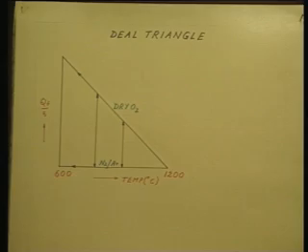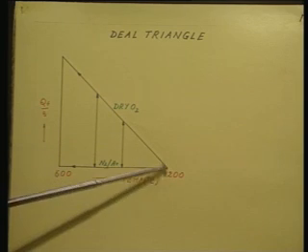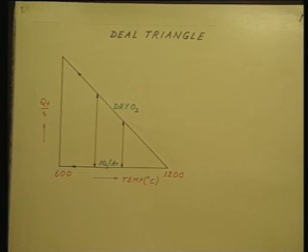So, this is actually depicted here in this figure. This is called the Deal triangle, named after B. E. Deal, who was one of the pioneers in the silicon dioxide oxidation process. What we have here is on this axis the fixed oxide charge QF by Q. This Q is electronic charge, so it is a normalized value, and on this axis we have the temperature. So, you see from 600 degree centigrade to 1200 degree centigrade, that is the scale.